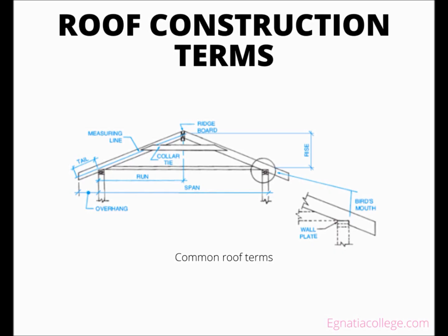Also, the roof decking that is usually sheets of 4-foot wide material will have only 2-foot wide scraps if the width of the roof is a multiple of 2 feet. The 2-foot scraps can usually be used on the next row of decking. Steeper roofs have more roof area than do low-sloped roofs.